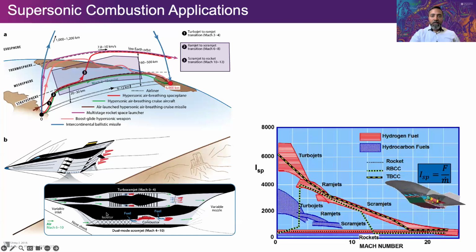Now, on the bottom, you see there are two engines embedded, and I won't detail what they are here because I'm going to talk to the one that's on the bottom in quite some detail in this talk. But I'll draw your attention to the graphic on the right bottom, which is looking at a performance metric called specific impulse, ISP for short, which is nothing but the thrust that an engine might produce over the fuel flow rate of propellant. And as you can gauge from that terminology, this is more of a rocket performance metric that is applied across the board to assess different engines.